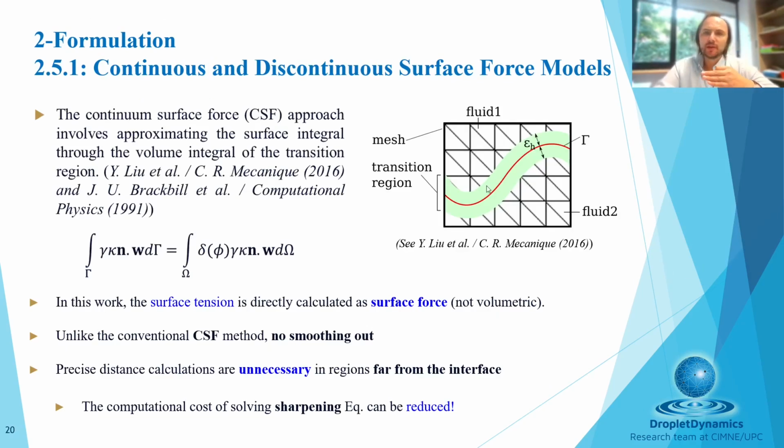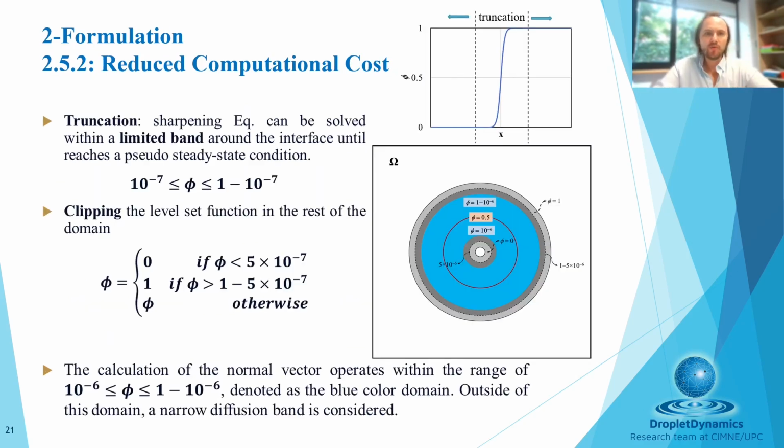Once again, what is the main advantage of our combination of conservative level set with our enriched finite element? Conservative level set also has some issues with the computation of normals far away from the interface. But for us, since we are representing the discontinuity exactly over the cut elements, we actually do not care what's happening far away from the interface. So we don't spread the surface tension over a finite region. We have everything exactly on this zero thickness, and we only care about having our interface and the normals just at the interface and maybe just the adjacent element.